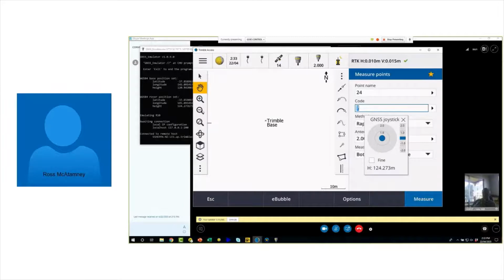You can also have a secondary set where you want a set user zoom extent. So you might be working on a particular building, part of that site, and that's our area of interest, but there's a larger property, and then 5 kilometers away we have the base station. We can set a user zoom extent, and then rather than coming out to wherever that base might be at 10 kilometers, when I hit this, I come back down to my 50 meters. So it's overridden the default extents.